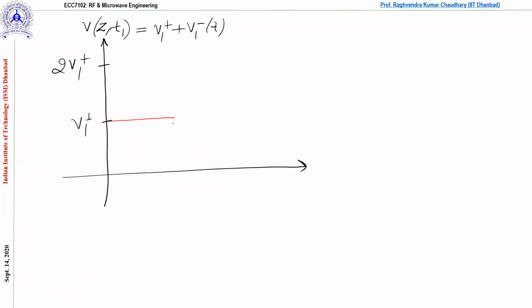Now if you draw it, it will be like this. There will be a pulse kind of shape up to z1 at any location, let's say, and after that it will start increasing exponentially like this, up to L. This is, let's say, L. Correct, it is going back towards the source side. So here t1 is 2T minus z1 over u.